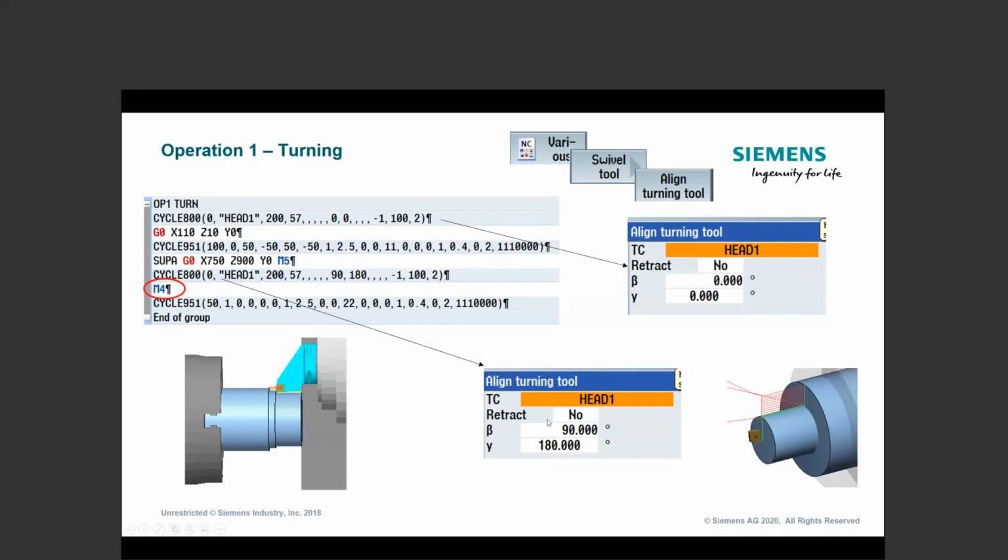And then when I go down to do my next orientation, as you saw quickly when I did the first overview, I wanted to swing down to 90, and I knew I had to spin my spindle. So generally with the spindle, you're only ever going to do 0 or 180, right? I'm only flipping it 180 over, and the only time you would have anything other than that would be if you were using like a multi-tool, but the multi-tool is going to handle that. So you're still using 0 or 180 because the multi-tool knows enough to say, well, 0 for that tool isn't actually 0.